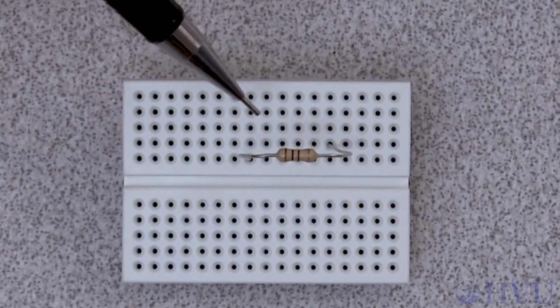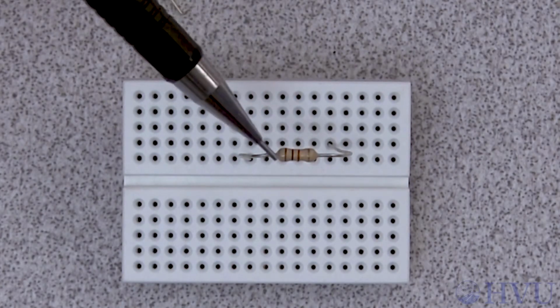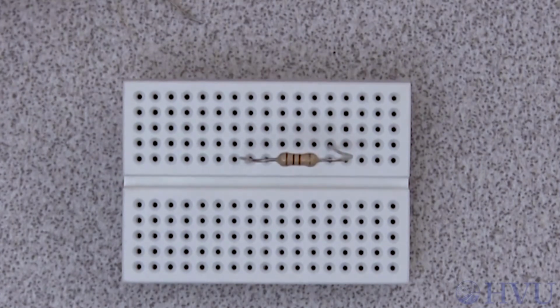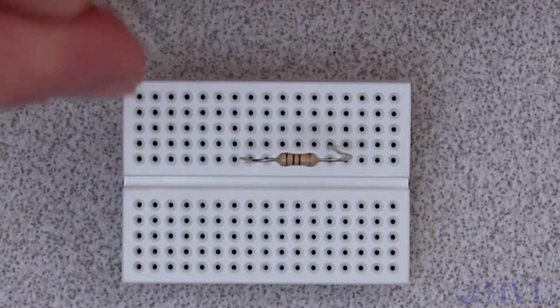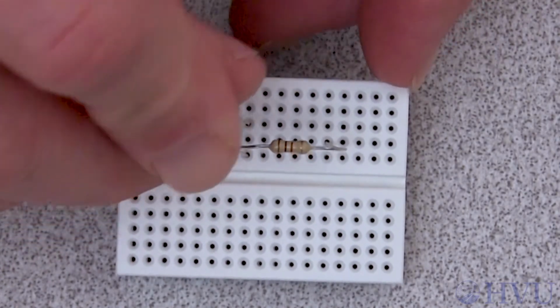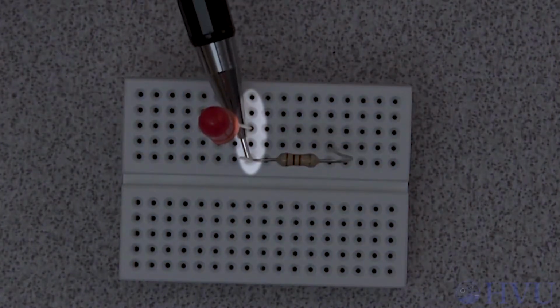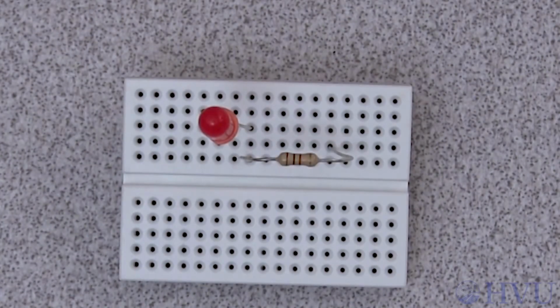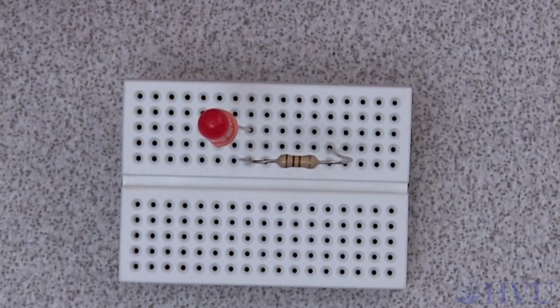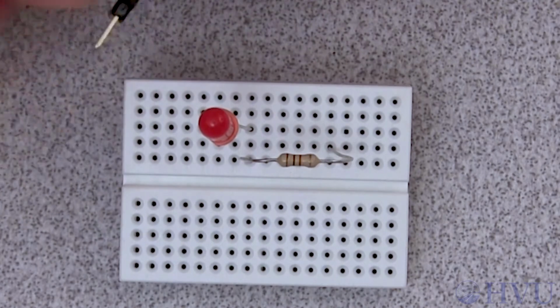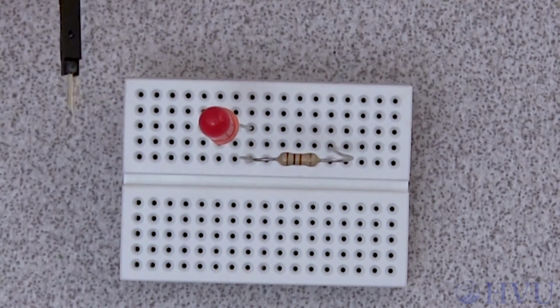Our resistor has a resistance of 100 ohms. Its color bands are brown, black, brown, gold. We'll connect the LED's anode to the resistor. Remember that the anode is the longer of the diode's terminals. By plugging the anode into a hole in the breadboard that's in the same row as one of the terminals of the resistor. Now if we're using V+ to apply our positive voltage, we plug the red wire into a hole in the breadboard that's in the same row as one of the resistor's terminals.